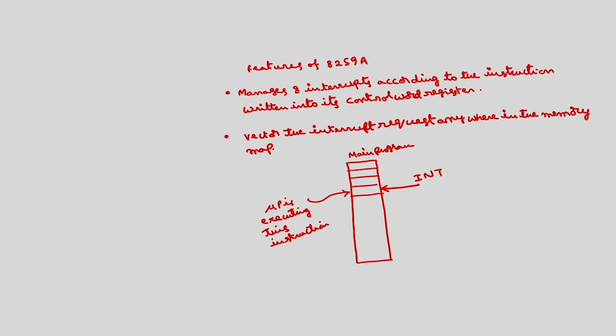the microprocessor will complete the execution of the current instruction, then it saves the contents of the instruction pointer onto the stack, and then it jumps to a location called the interrupt branch address, which is the starting address of the interrupt service subroutine.